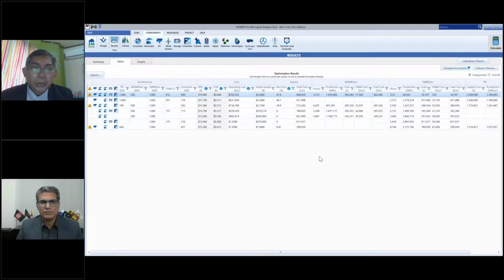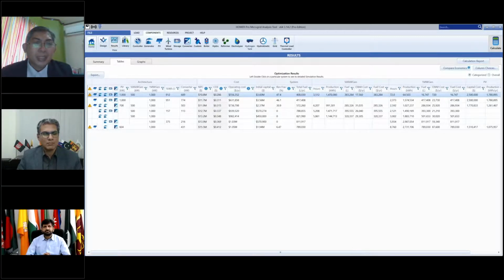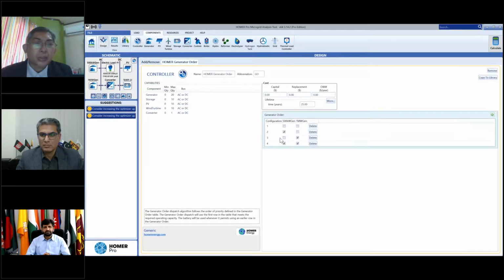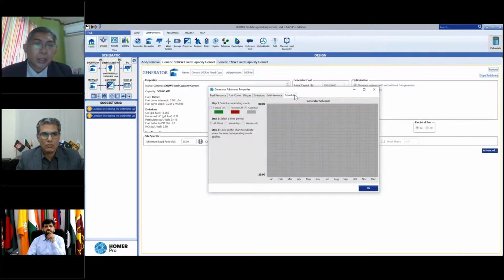Peter, would you like to show the part where you can schedule the genset operation? Because there could be participants who have a specific schedule of which genset operates at what time. Oh, you're talking about scheduling them. I see. Yes, I misunderstood. So you can click on the genset, and you can go to the advanced part, and yes, there. So you can force it. Okay, good point, Silver.